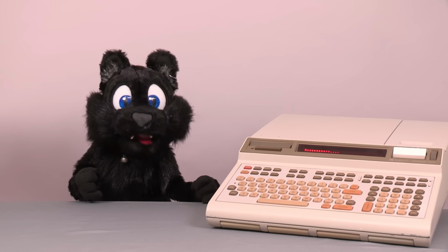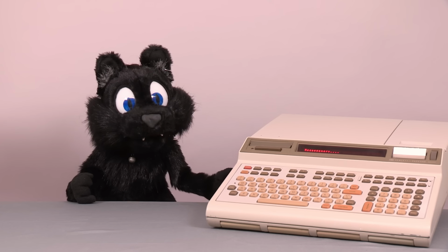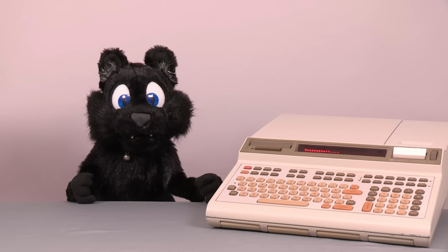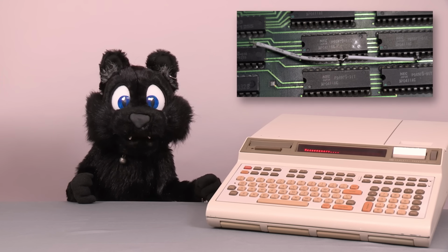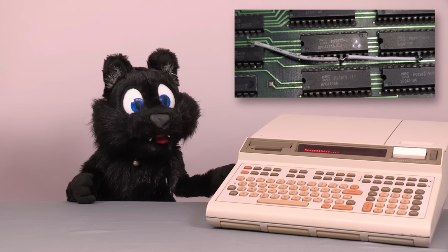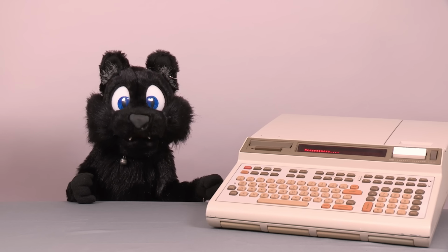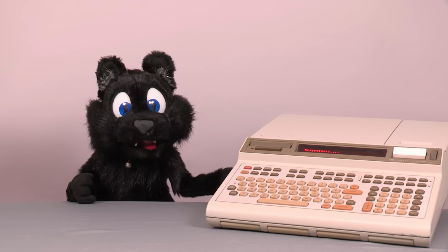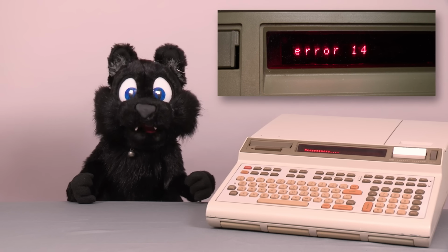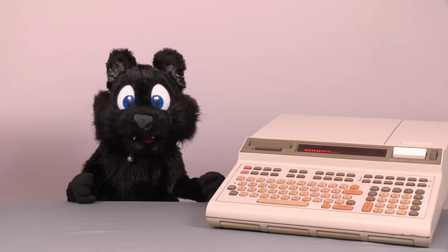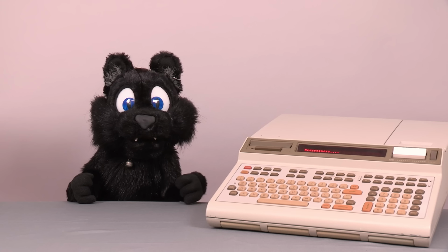First sub-project, the RAM modules. As I said in the original project series, the RAM boards I got all had their issues. And I just so made one of them work. There was a bad trace for data bit 6 on it, hence the botch wire. It does work, but occasionally the system fails to boot, and I also keep getting error 14, which translates to program structure destroyed. These odd errors at odd times make me think that the RAM is anything but reliable.